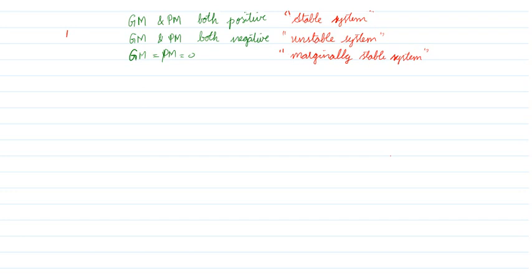Okay, that's it. Now I think we can roughly see how to plot quickly. You can see how we can plot a polar plot for a given function, G of s given as 2 by s, (s plus 2), (s plus 4). Roughly, not an exact plot. How many factors are there?